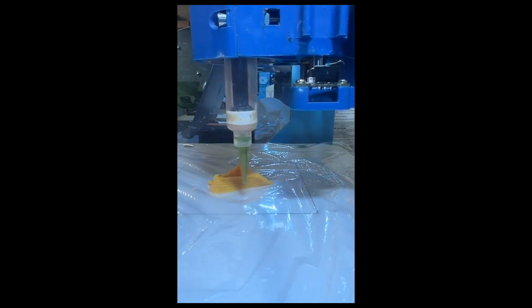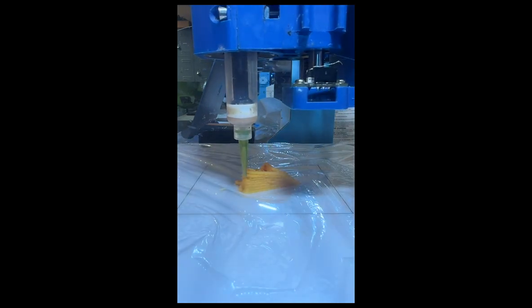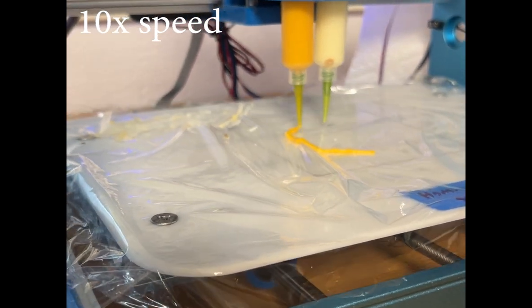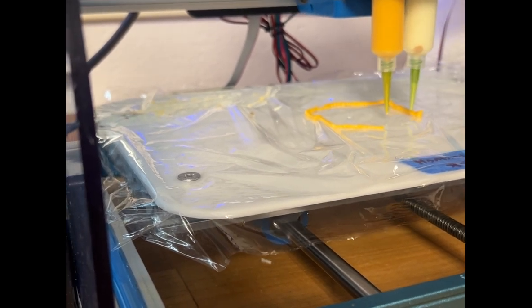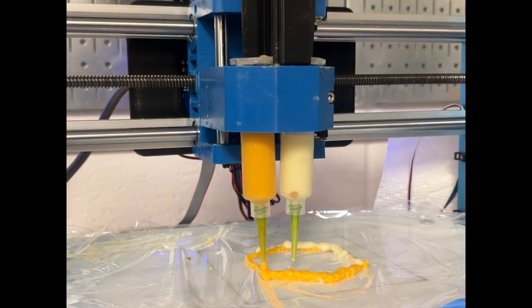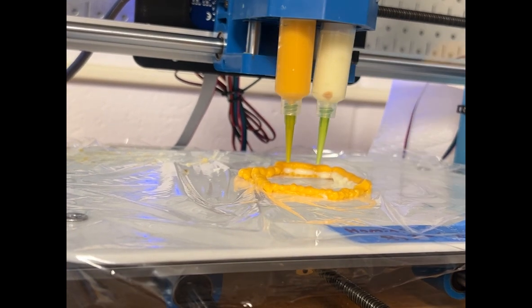I would also be wary of the saran wrap. Make sure that there aren't any bumps in it and that it's as flat as possible. If there are bumps, then it will be really hard to stack the layers on top of each other. In addition, be wary of the offset between the two nozzles if you're using both of the extruders, as this can mess up the positioning of your shape. So just double check it using the G code and make sure that it makes sense that they will overlap with each other.